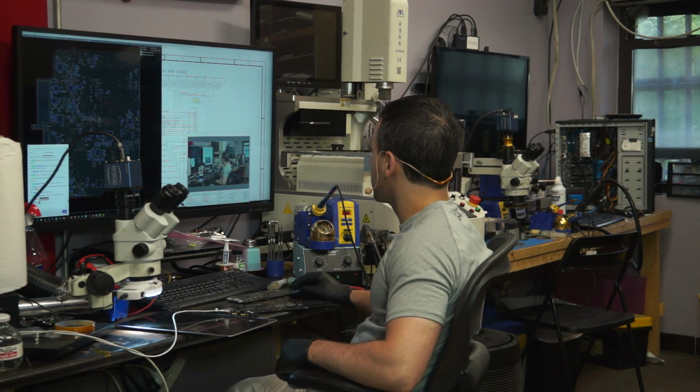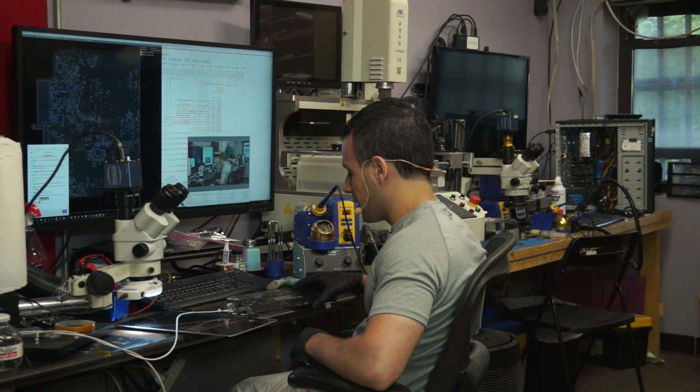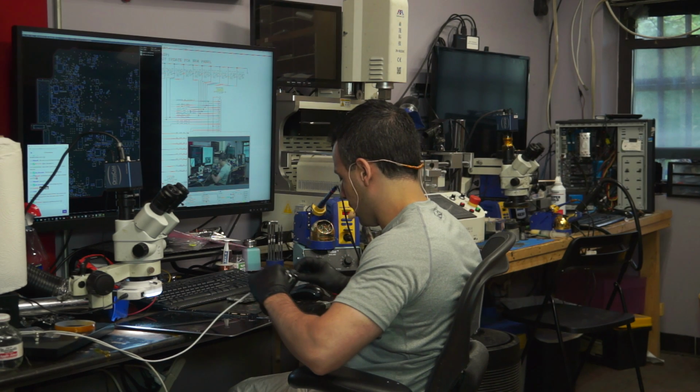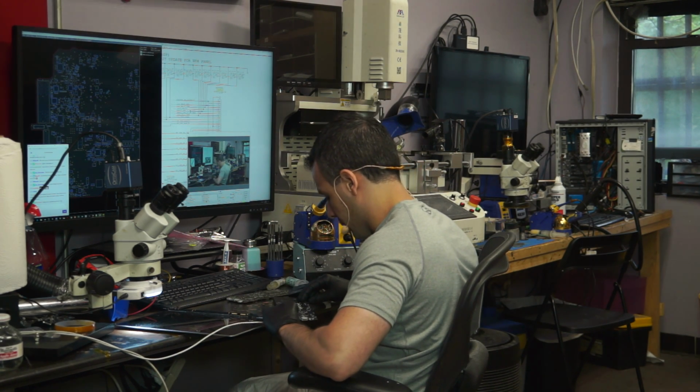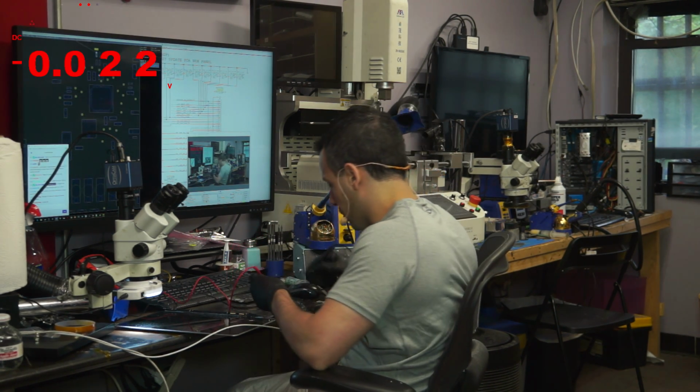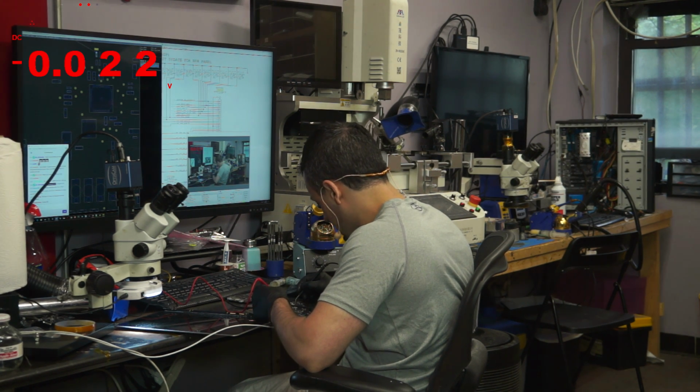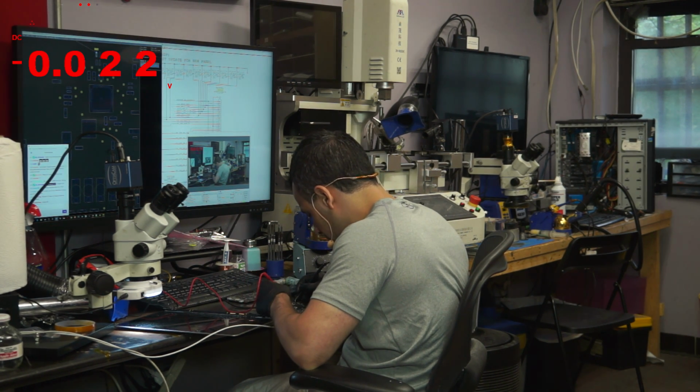J8300, that's going to be on pins 3 and 4, right? And the only corrosion on this entire board was on backlight SD on the LED driver, which was totally fixed. Perhaps I2C doesn't happen because of corroded paths. We measured the path between the screen connector and the I2C line of the LED driver already.